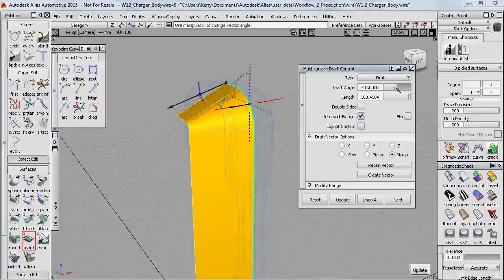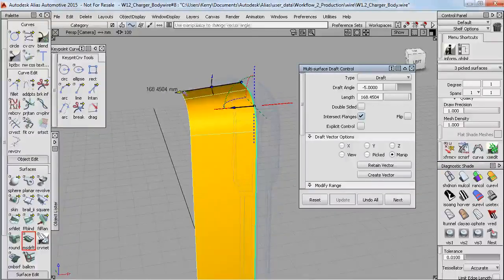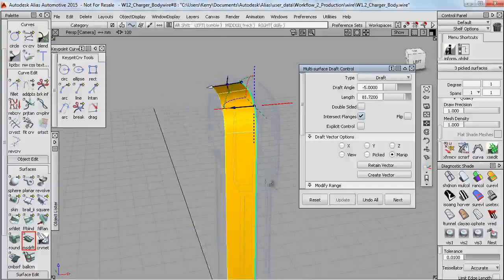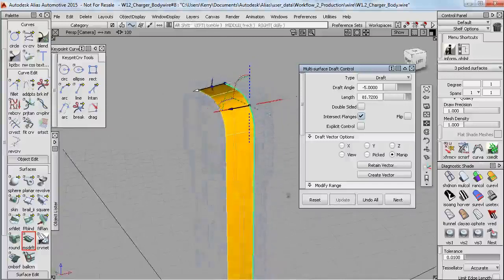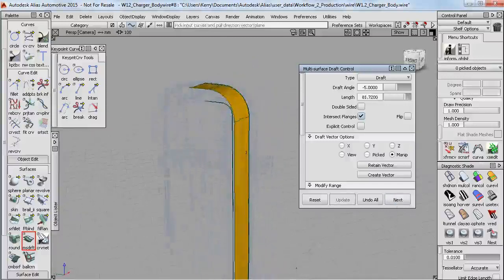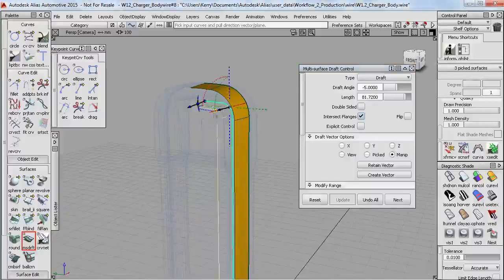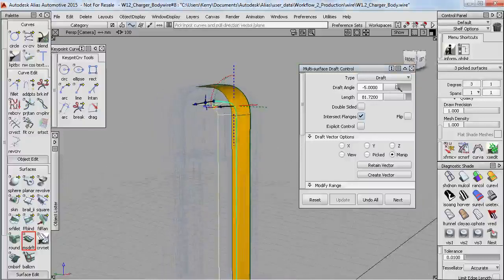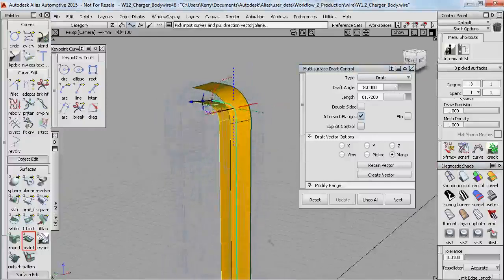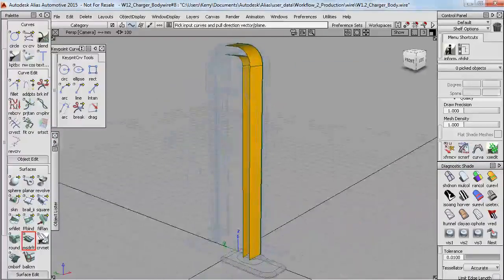And it's an outdoor piece of furniture, so it'll probably have a strong texture on the moulding. So I'll do quite a large one so you can see the effect as well. And just adjust the length a bit. But I want to make sure it'll overshoot that front surface. So I can do the next one along this inner edge, and this time the draft angle needs to go the other way, so I'll make the value positive. So now all the surfaces should pull out of a mould.